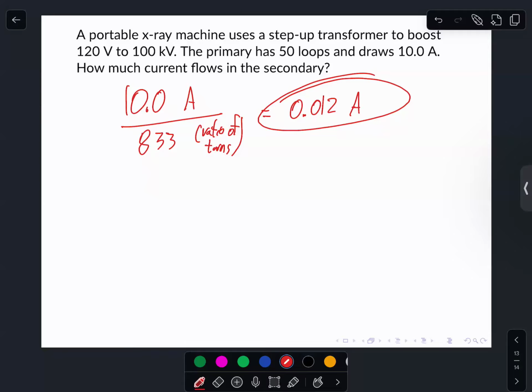Okay, let's try this again. The current that actually flowed was not just straight from the applied voltage. There were really two voltages fighting, adding together. You get a very different result. The applied voltage and the induced voltage together drove that current. So the big takeaway is that induced voltage pushes on the original current that produced it, as well as any other coils that are nearby.